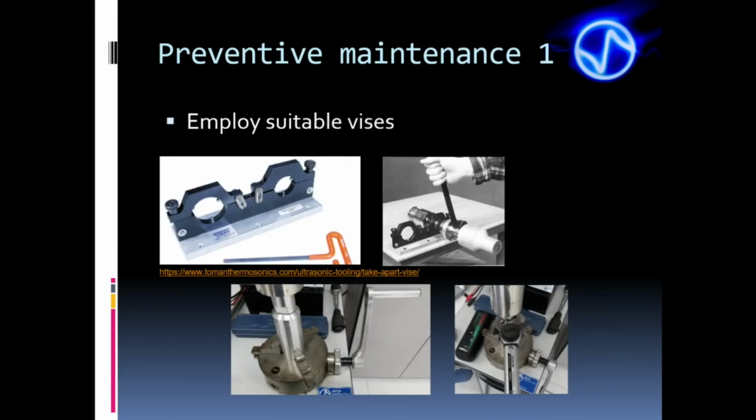Now, we know how to do preventive maintenance 1 to keep the coupling of the stack's elements optimized. However, to perform the procedures, it's necessary to use suitable tools in order not to damage the stack during the restoring process. Remember, defects in the stack element surface can affect its performance and are crack nucleators. Custom vices for acoustic stacks are recommended. We can find some at the link below.